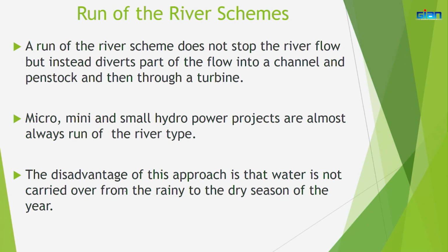So, run-of-river schemes, as the name suggests, use the water running in the river and utilize the water to impart the energy to a turbine, and then directly put the water back to the river. There is no water storage, no water collection, and therefore these projects are much more environmentally viable and less polluting or less interfering compared to large hydropower plants. And this small hydropower, which might be pico hydro, micro hydro, mini hydro, whatever the name suggests, 95% or even over that are run-of-river power plants.